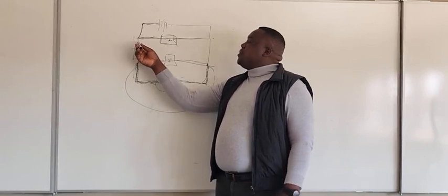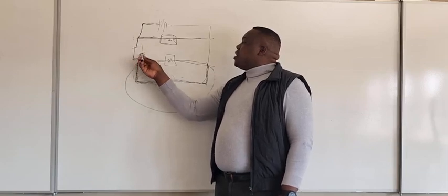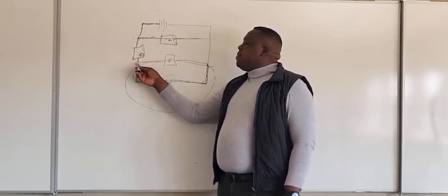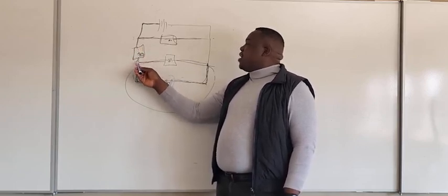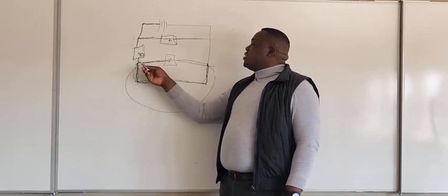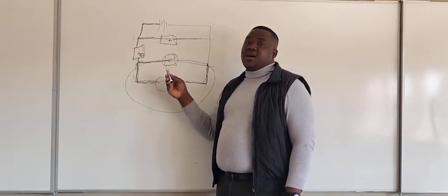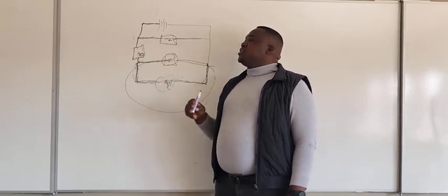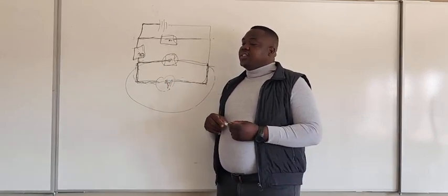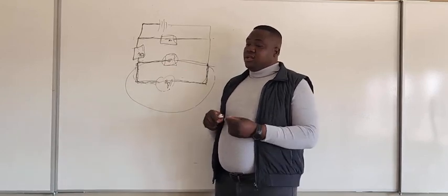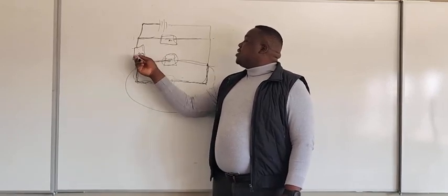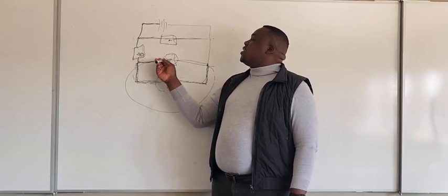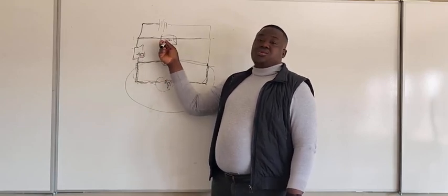It's not the same cable, I mean. Another cable extends. It moves straight, then it connects this resistor. Then again, the very same cable here that connected this resistor, it turned here and connected the second resistor. Meaning that one cable is carrying two resistors. So it means these two resistors are in series with each other, but they are parallel to this one.